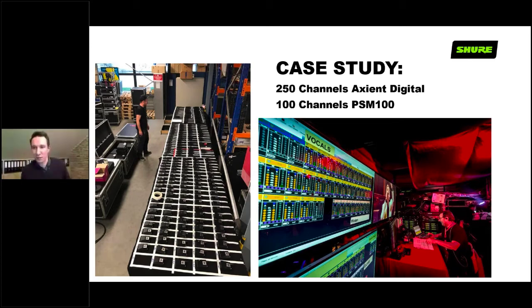Obviously, when you start doing things like that, we explained the basic fundamentals: calculate your cable losses, calculate your splitter losses, and it's fundamental that you target that plus minus 5 dB receive level at every receiver. But I wanted to show this as a nice example of 350 channels that were all run on 3 antennas. And that's basically the only realistic, accurate way of doing this.